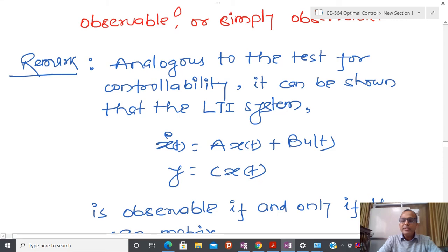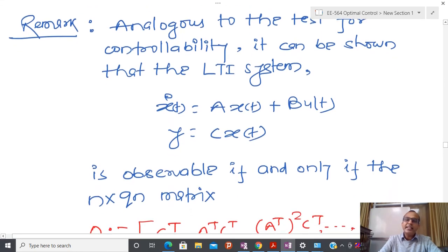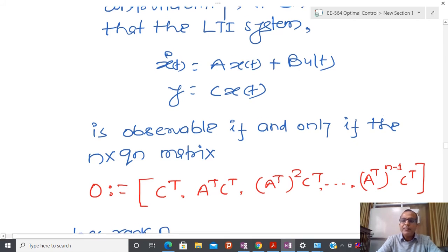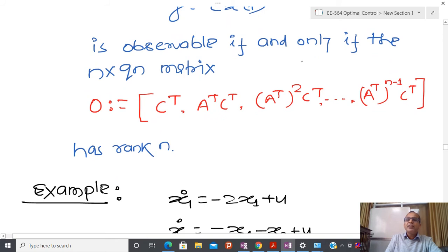And now you can see here that I have again taken an LTI system. I again comment that for a general class of systems, a necessary and sufficient condition for observability is difficult. But particularly for an LTI system, by checking this observability matrix, one can talk about the observability of the system. It means if I know the output, it is possible to understand all the initial conditions of the state. And if I know the initial condition, and the input u(t), then I can obviously talk about all the future behavior of the system.